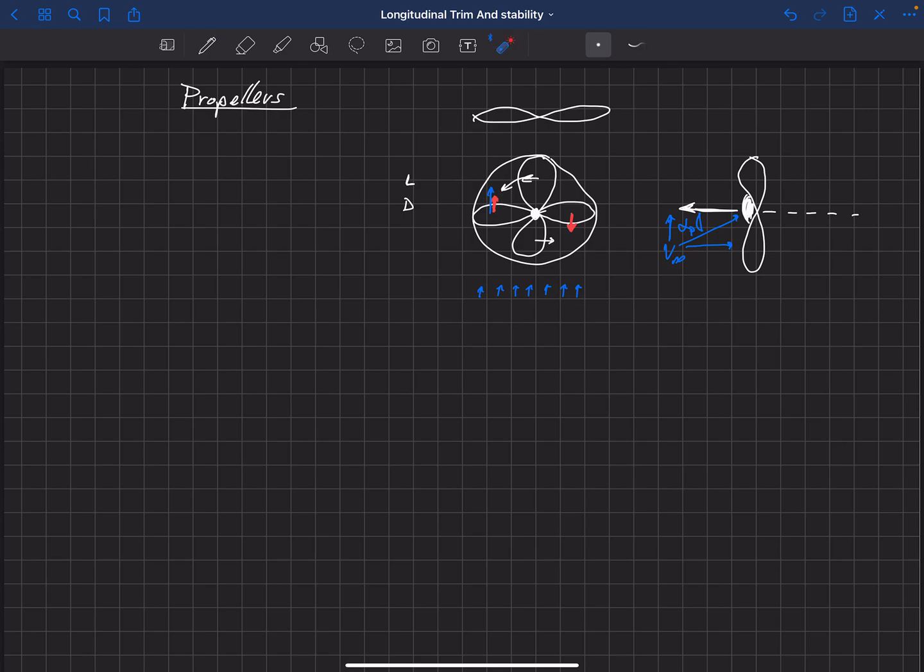And let's look at the drag on this blade. As this rotates around, it's now moving in the same direction as this velocity. So the fact that we have some velocity in this direction actually decreases the drag, or the dynamic pressure, that the blade sees on that side. And so because we're decreasing dynamic pressure, we also decrease the drag. So there's just a little tiny drag vector there that's smaller than the red drag vector.